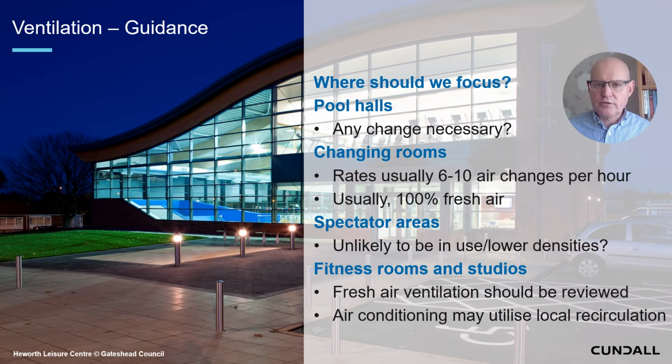So where does that take us? Pool halls, good levels of ventilation, generally way in excess of minimum recommendations, and we'd consider to be fairly low risk as they are currently designed and operated. Similar for changing rooms, generally very well ventilated, usually 100% fresh air, fairly low risk. Spectator areas, normally part of the pool hall, so part of the same ventilation system, and in the current scenario, unlikely to be in use or certainly with restricted occupation.